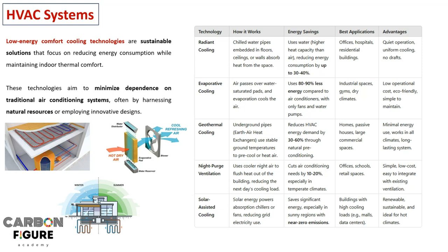Sorry, it uses water, reducing energy consumption. Water has a higher heat capacity than air, so that is why water is being used. That is the logic, right? In evaporative cooling, air passes over water-saturated pads and evaporation cools the air, right?